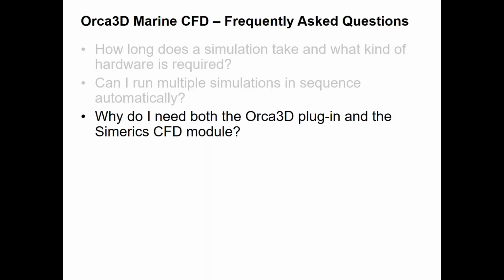Orca provides a straightforward and familiar user interface, much like the Rhino interface, to allow you to enter much of the required input for the analysis. It also helps to set up the CAD surface meshing process with the optimal mesh parameters out of Rhino. And it provides, of course, the hydrostatics capability necessary to float the vessel to equilibrium for the initial condition.